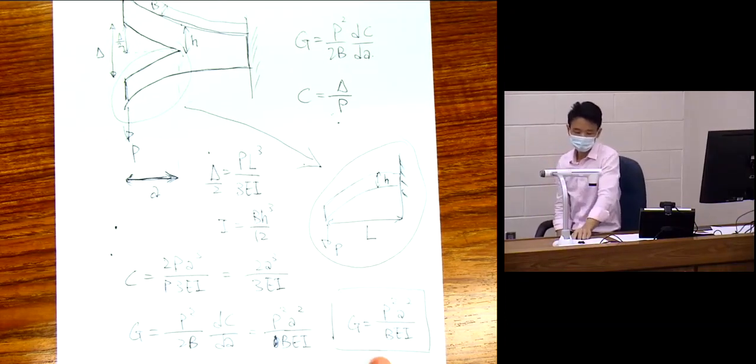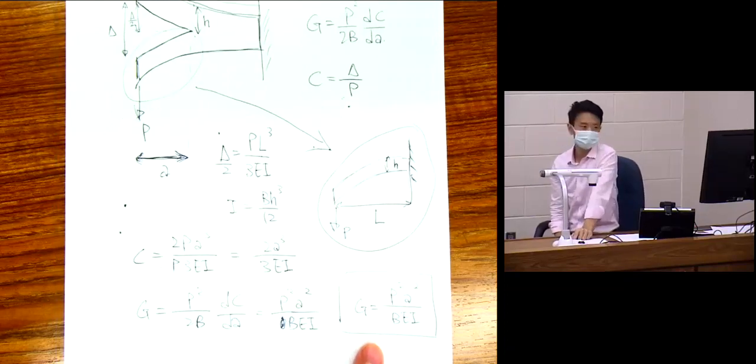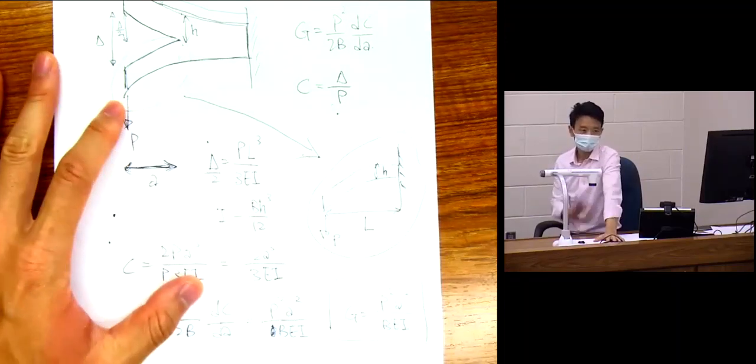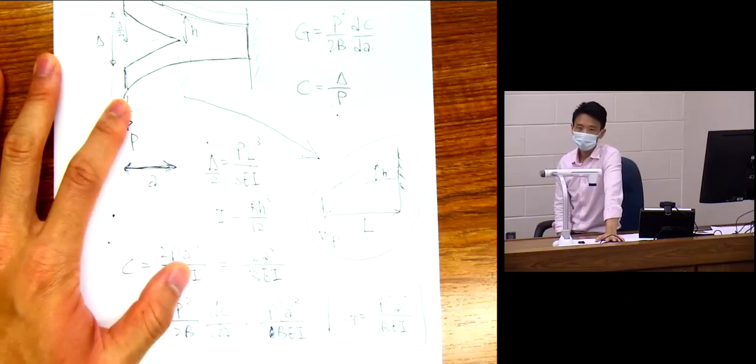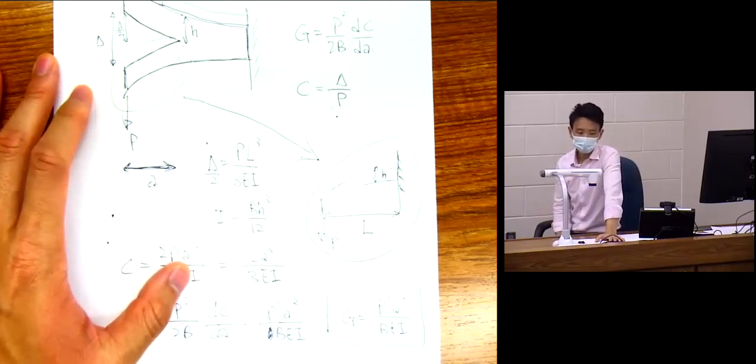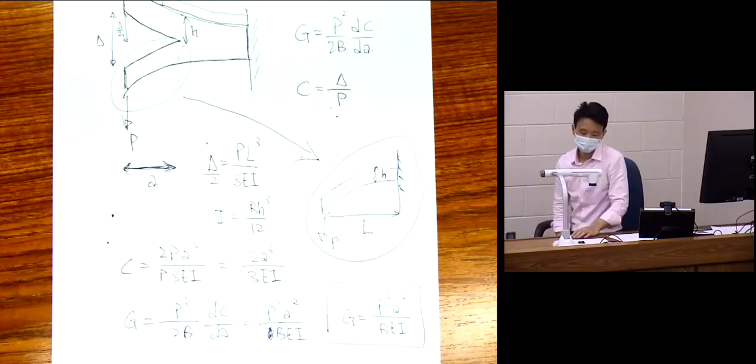Now, this sort of analytical solution can be solved for some simple problems. So analytically, we derive this simple result for a certain number of geometries. I'll show you more of what we can compute and what simple configurations people use for experiments, because we don't want to always go to finite element analysis just to measure the fracture energy.